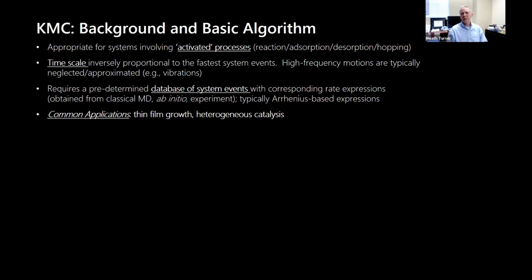The time scale tends to be inversely proportional to the fastest system events. So if you have high frequency motions in your system, like a lot of vibrations, you're probably going to want to neglect or approximate those motions, because those will end up overwhelming your system and severely limiting what you can do with this approach.